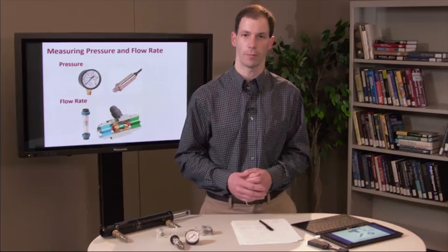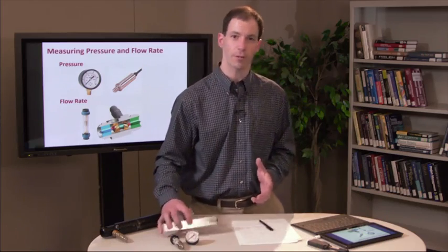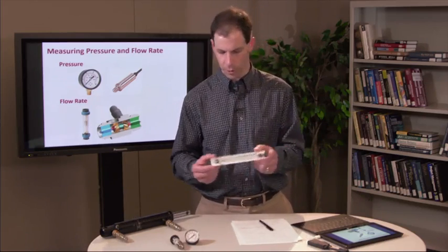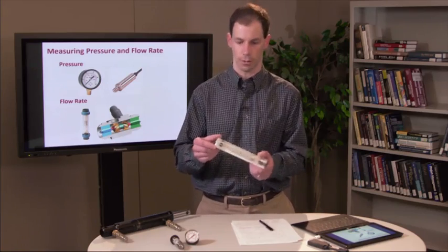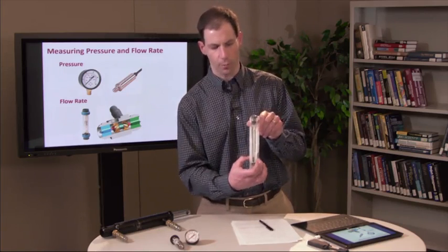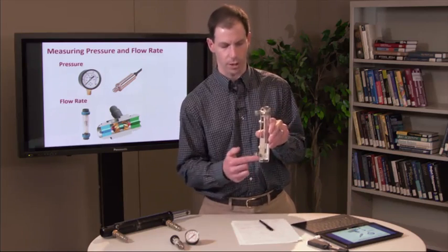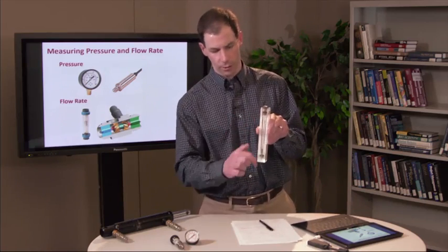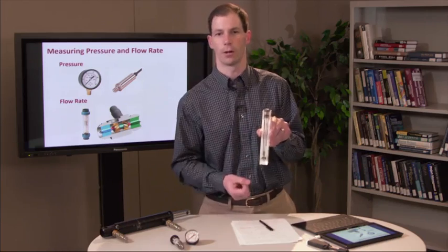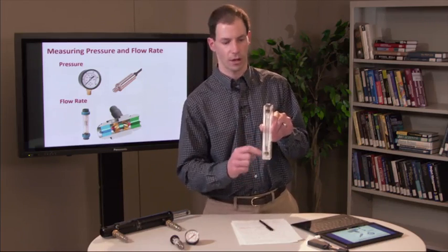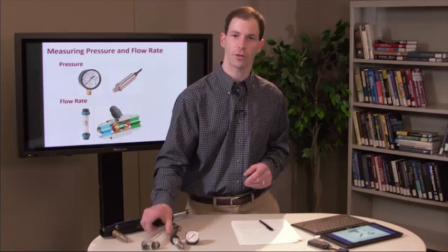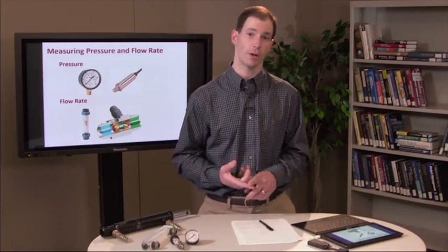Now, for measuring flow, there's a number of different devices. One of the simplest is what we call a rotameter. This is an example of a rotameter, and you can see this little slug that is sliding back and forth. This tube-shaped area in here is conical, so it's a smaller diameter at the bottom and larger at the top. I've got flow coming in here, coming out up here. So I've got gravitational force acting downward and the viscous force of the fluid acting upward. When those balance, the slug stays in one location, and I can measure the flow off the top of that slug.